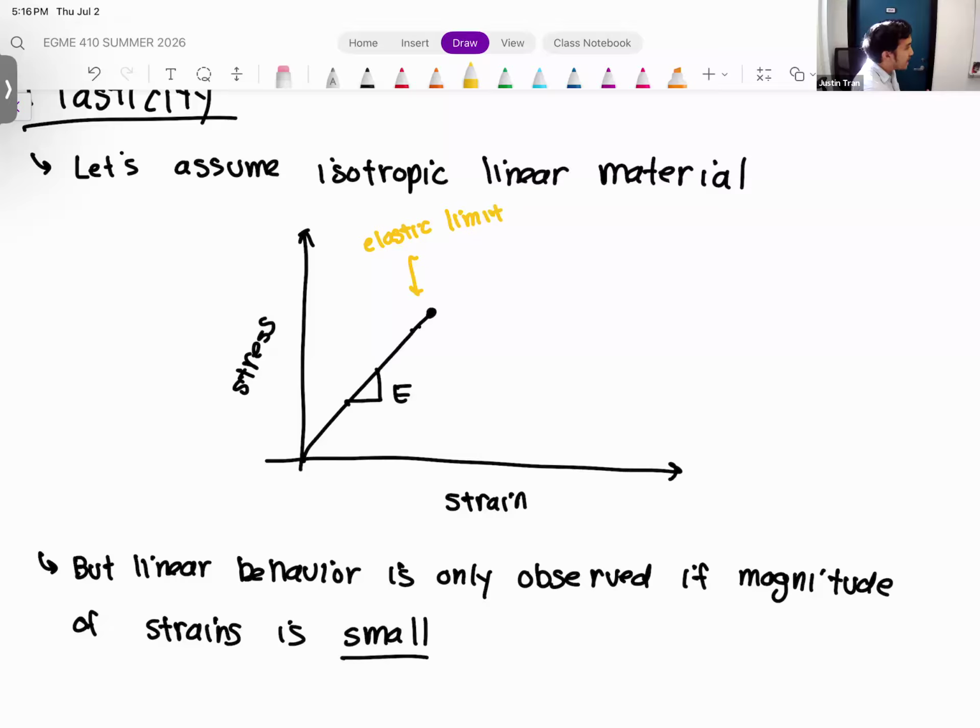So the elastic limit is the maximum stress that the material can sustain while it's still having this linear relationship. You can also say that it's the maximum strain as well. Past that elastic limit, our stress strain curve starts to change shape. Instead of being a nice linear line, the curve starts to taper off, so it almost starts to look like the curve of the square root of x, for this region right here. If we look past this region where that linearity starts to get broken, that is what we call the plastic region of deformation.